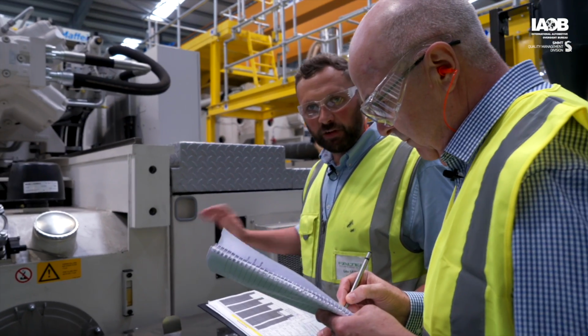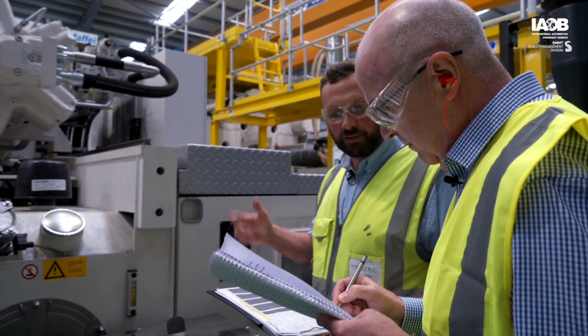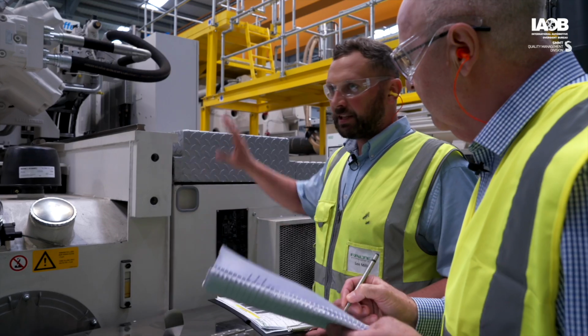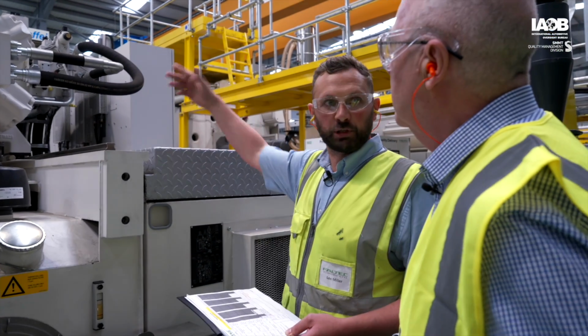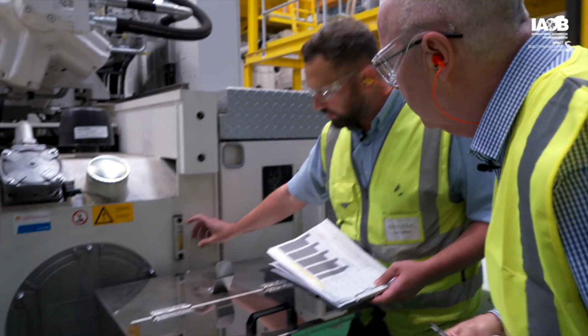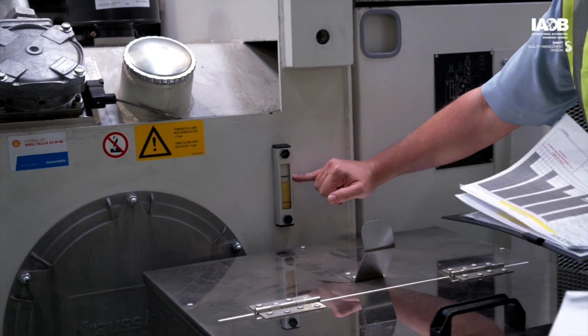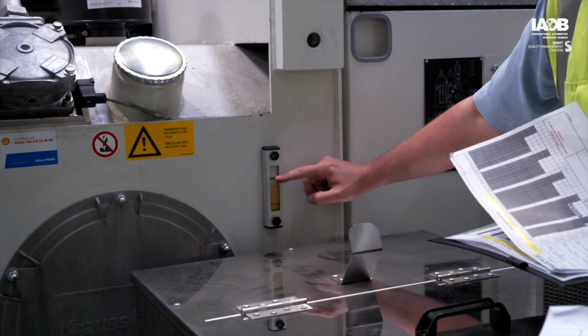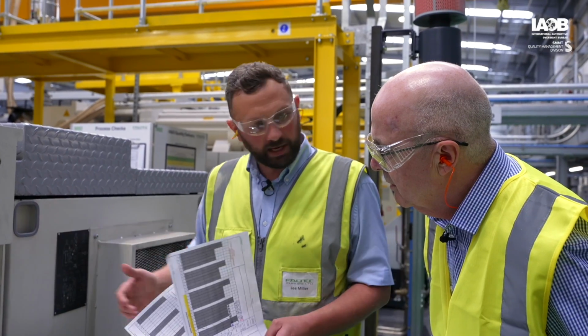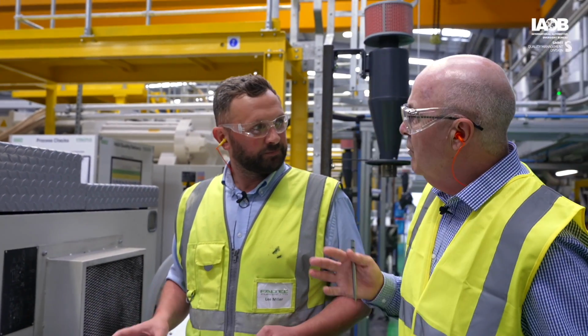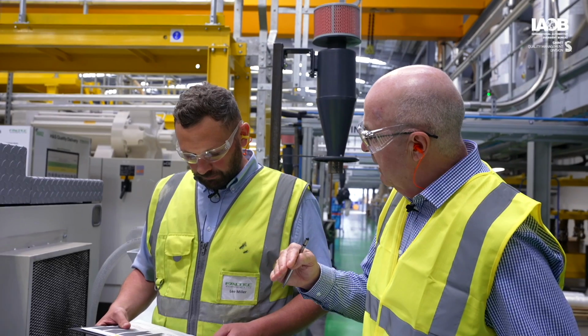This is the oil level for the machine, which is obviously critical to the function of the machine working. This check's got to be done when the mold's closed, which is closed now. Okay. So this is your sight glass reading. So that's low level, that's high level. Okay. So you always want to be around this area here. As you can see, the mold's open, the oil will move. Okay. And what would be your action if the level goes below the minimum?